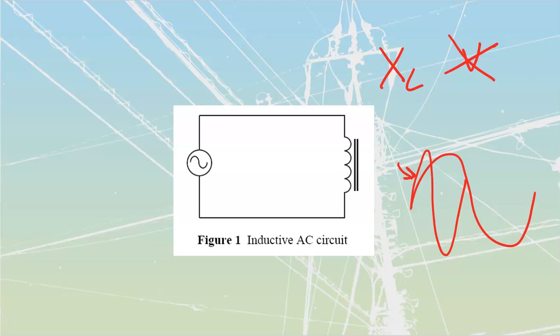The problem is that this current is now only happening over half the amount of time. Before, I had this whole slope that took all the way up to here. That's how long it took. Now we've cut that time in half. Once again, if I take a look at my formulas, E = -L ΔI/ΔT, what I'm going to see is that I have halved my change in time, right? The current stays the same. The L stays the same for that one, but I've changed the amount of time that I have to react.